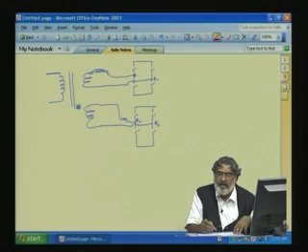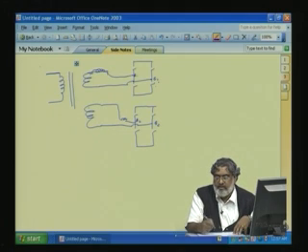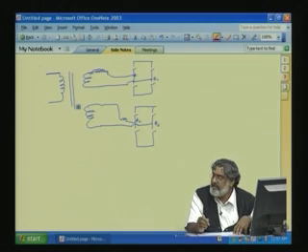For A1 and B1, we will use the same reference wave, that is modulating wave, same sine wave, but the triangle waves for A1 and B1 are 180 degree phase shifted. For B1 the switching sequence is reversed. So, what is for S1, you will use it for the bottom switch of B1. Then for the second converter, the same modulating signal we use, but the triangular waveforms for A2 B2 are 180 degree phase shifted, but A1 and A2 are 90 degree phase shifted.